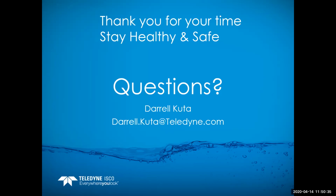What's the lowest velocity that can accurately be measured with a Doppler sensor? What I've found over the years with the Doppler sensors is around 0.3 foot per second is about as low as I'd want to go. But I'd prefer to stay around 0.5 foot per second or higher with the Doppler sensors.